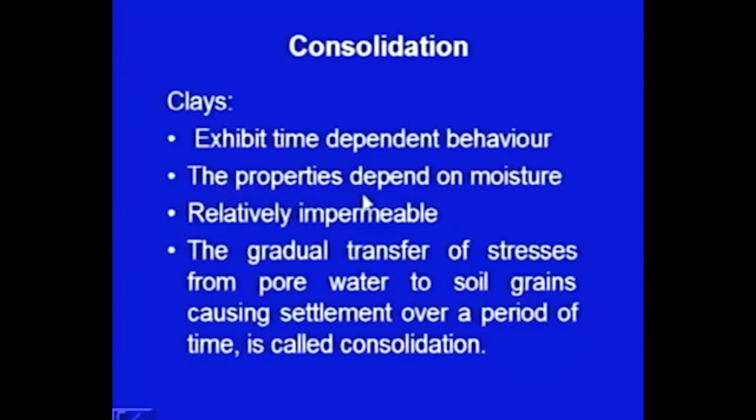Secondly, the properties depend on the moisture content. So, water is very important, the moisture is very important as far as clays are concerned. Third point about these soils is that they are relatively impermeable. So, if you apply load on the soil mass which is predominantly clay, then water will not squeeze out very easily, it will take time, they are not permeable, and this will create problems. This is the reason why they show the time dependent behavior.